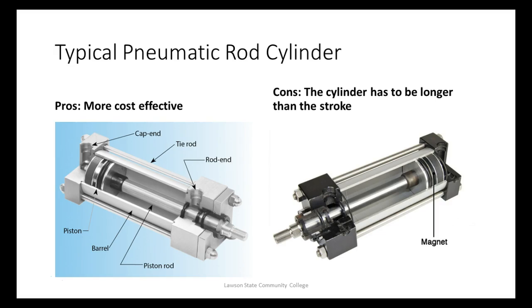This is the inside of a cylinder. So this is our cylinder right here. What does our cylinder have on it? Magnet. So now we can use external magnetic sensors to sense when this thing's in a certain position. And sometimes those are adjustable, which means somebody can do what? They can adjust them. And you'd be surprised, people get out there not knowing what they're doing, and something stops working. So what do they start doing? They adjust knobs. We used to call them knob dickers.